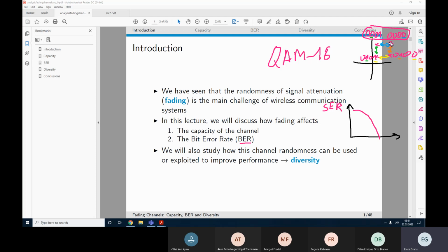Needless to say, errors over shorter distance happen much more often than errors over this distance. So here, if, for example, this error would occur, that would give in total 2 bit errors. So symbol error rate cannot always be directly expressed as the bit error rate. This depends on the noise, on the mapping, and other factors as well, so it's not that simple to recalculate this error.